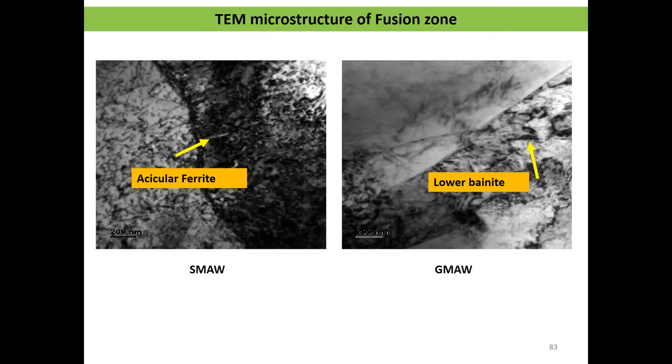Again, we confirmed acicular ferrite through the TEM images for the SMAW process, and lower bainite has been confirmed through the TEM images for the GMAW process.